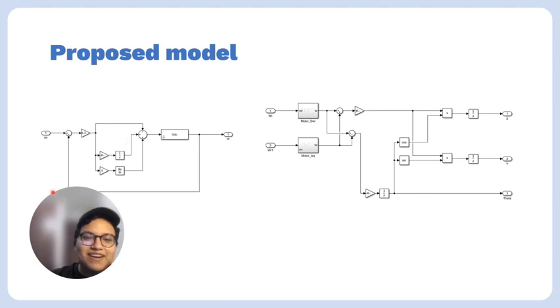Then we have here in this part the integration. Well, I'm sorry, I forgot to explain. Here we have the PID controller with its corresponding gains, and here is the implementation. When we have already done the PID controller for both motors, we combine it with the kinematic equations to obtain the derivative for x, y, and the direction. After that, we integrate the derivatives of x, y, and theta, which helps to accumulate the robot's displacement over time. This is important for tasks like navigation and mapping, where the robot's history of movements influences its future trajectory, or all its future actions.